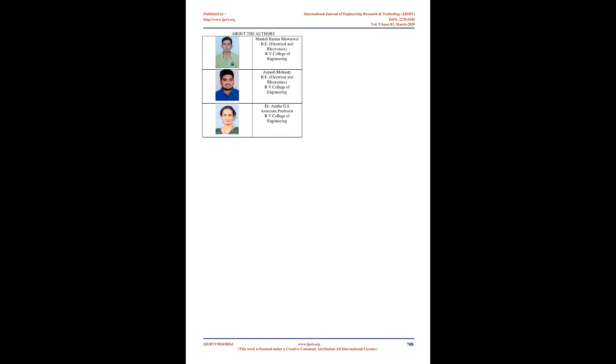Different battery conditions can be estimated with ease. The results have a high practical value. The artificial neural network can be implemented for any battery system provided enough training data is supplied. The SOC estimator based on the ANFIS technique succeeds in computing the SOC with relatively low error. 4 membership functions, 16 rules generated. Average testing error, 0.092696, plotted against the generated FIS.